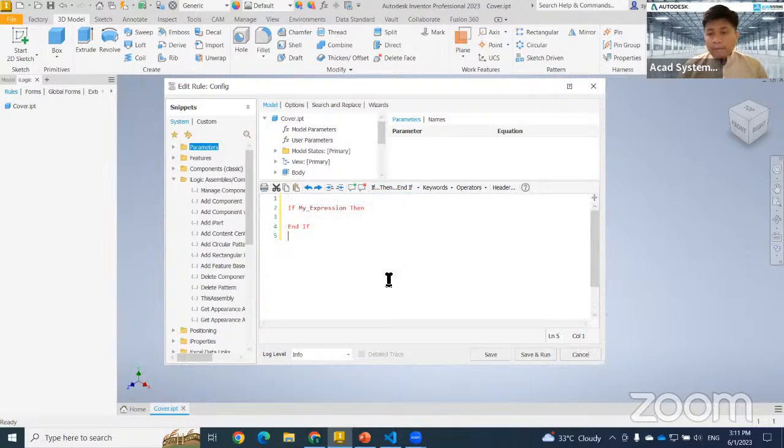Click. So right now I know that I want to use a proper parameter. For my expression, I need to double click, go to my user parameter, because extended will be in here. Right click and capture current state. This one I don't need, so I just want to make it: if extended yes, then.